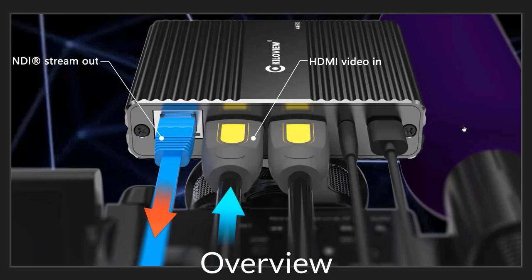Kiloview N20 is a combination of encoding and decoding. The factory default is encoding mode. Normally, as shown in the picture, connect the HDMI video source. Connect the Ethernet. Plug in the power cord to start this device until 3 work indicators light up. The device starts working. Now in this network, other NDI-compatible software can discover this device.